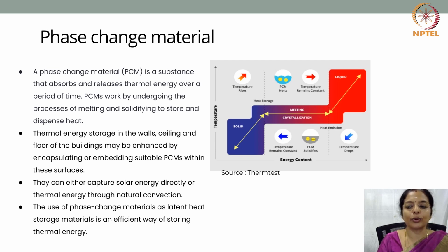Increasing the thermal storage capacity of building can increase human comfort by decreasing the frequency of internal air temperature swings so that indoor air temperature is closer to the desired temperature for a longer period of time. This system provides a valuable solution for correcting the difference between the supply and demand of energy.